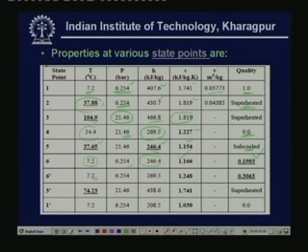And point 6 dash is for the SSS cycle without liquid suction heat exchanger. So, here again the temperature is 7.2, pressure is 6.254, and the enthalpy here is the enthalpy at the exit of the condenser, that is 269.5. Okay. So, again from the enthalpy value and the pressure you find the entropy value, and you also find the quality, which works out to be 0.3063.